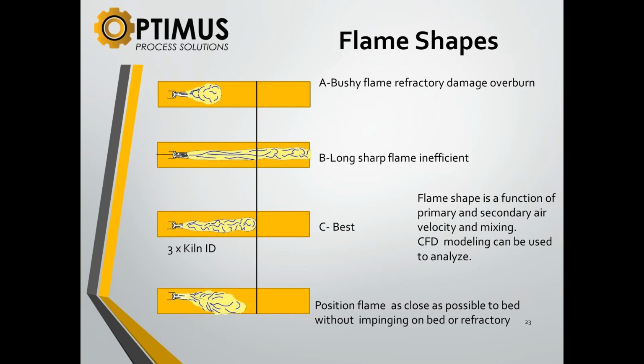Well, if you go outside and get your optical camera and you look at the side of a kiln, you can see many times, if there's not too much refractory in there, that the temperature of the shell is high and then gets lower. It cools down. So you can pretty well tell what the flame length is with the camera.